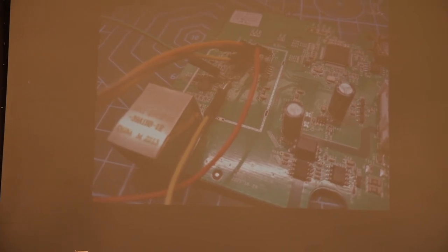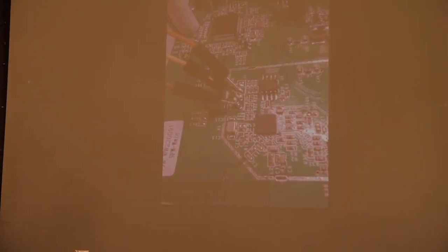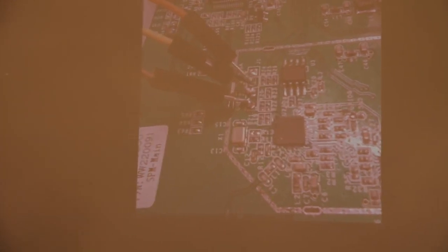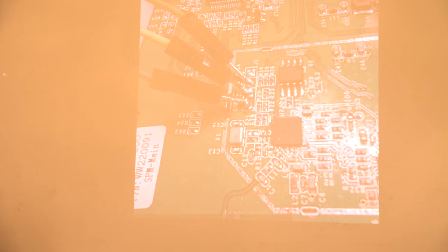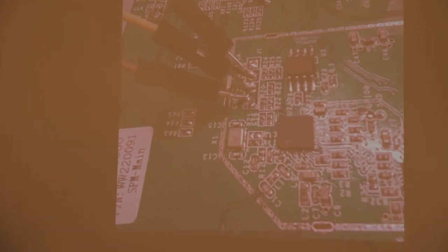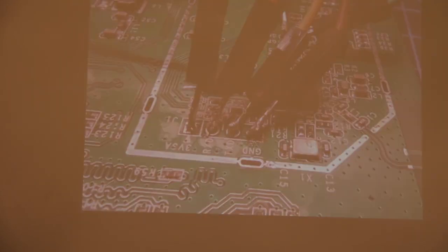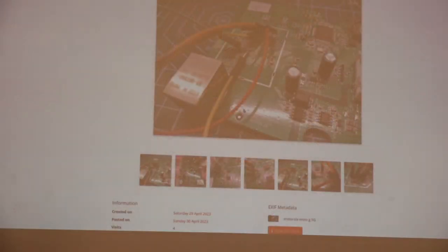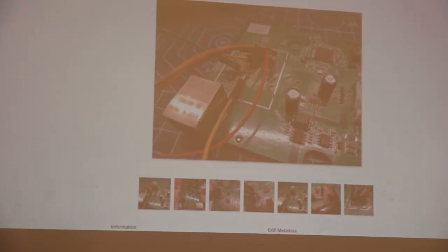Now, what the manufacturer does is, they give us these pins, like I was showing you. So these are the 3 volt, RX, TX, the serial port pins and the ground pin. So those are the 4 pins that we need to talk to this ESP32 microcontroller, and then be able to flash stuff onto it. So this is one of the ways I do it, by soldering these wires temporarily, and once it's flashed, then you can desolder these. So this is for the power meter.